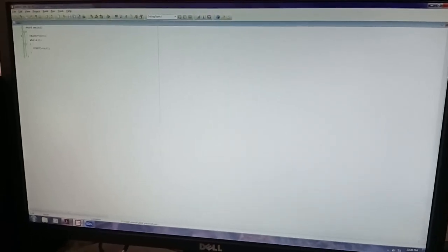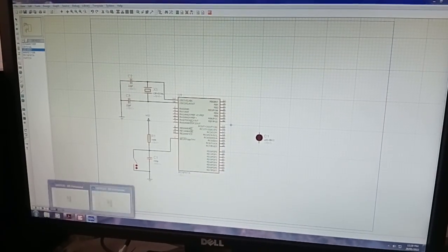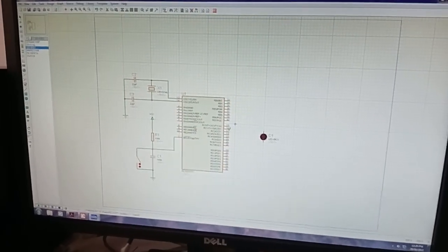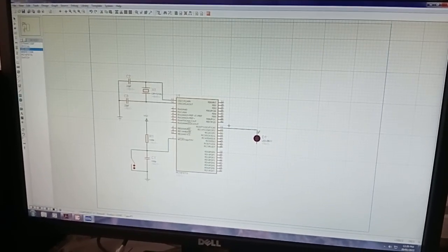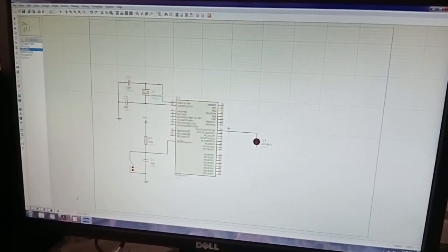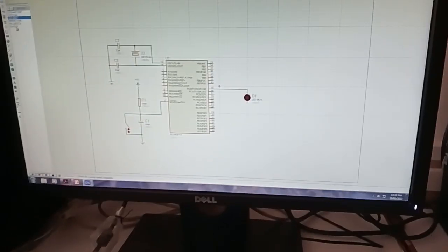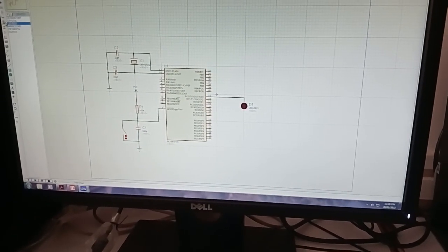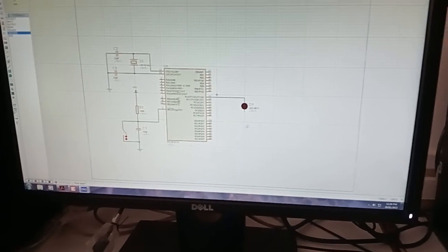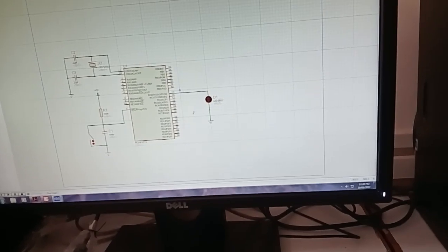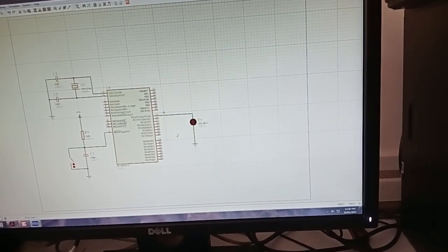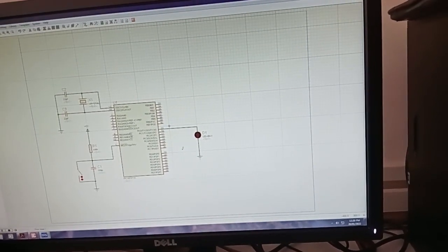Here in the program you use port C. Port C is in output mode. Then you should notice that you connect this LED to port C. If the port is changed, then some errors occur. Then the second pin of that LED is connected to ground. Then okay, this is the completed circuit diagram of interfacing the LED to the PIC microcontroller.